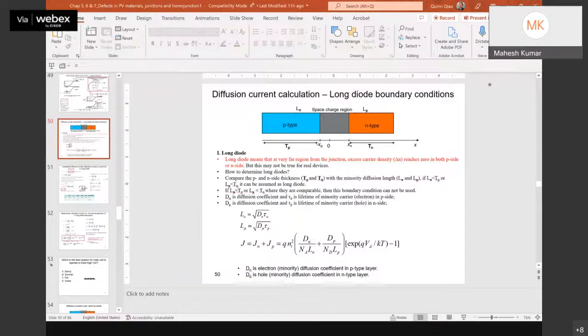Can you repeat the question? You mean the work function on which side? I see. See, you talk about a PN junction, heterojunction, right? When the Fermi levels align, and then you talk about the work function of the P side, the N side, both of them, or one of them, the work function of the materials does not change. The only thing that changes is inside the depletion region. Did you get my point? Outside the depletion region, you think about...